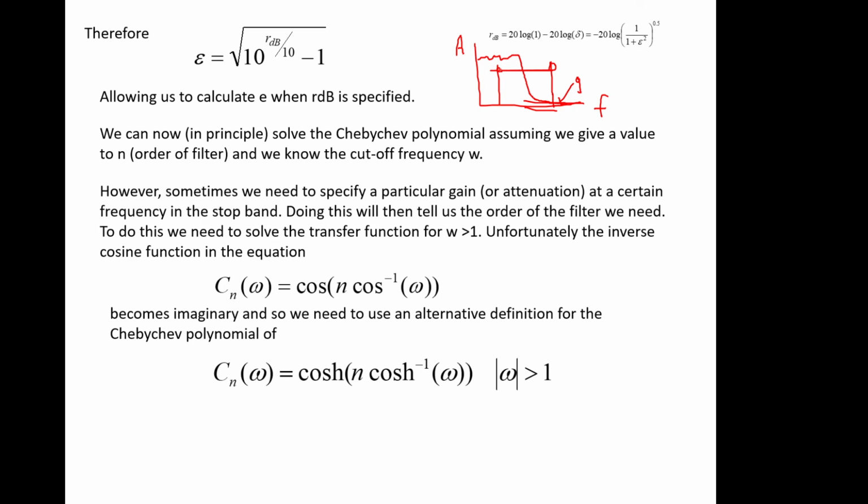So instead of saying I've got this cutoff frequency here and I've got this order here, I'm hoping for the best that this will be down at the right frequency, we can go the other way and say we need to know what the attenuation at this frequency is, what order of filter do we need to achieve that, and what cutoff frequency can we get away with. So that's all that meant.